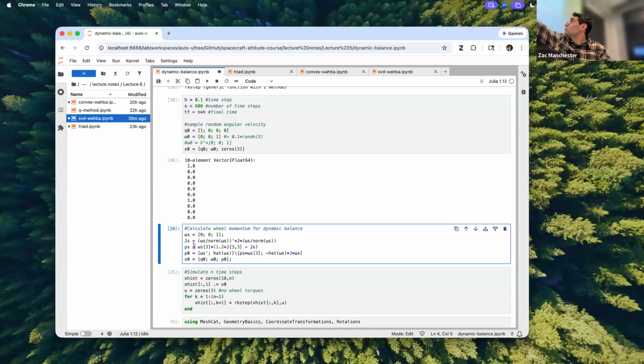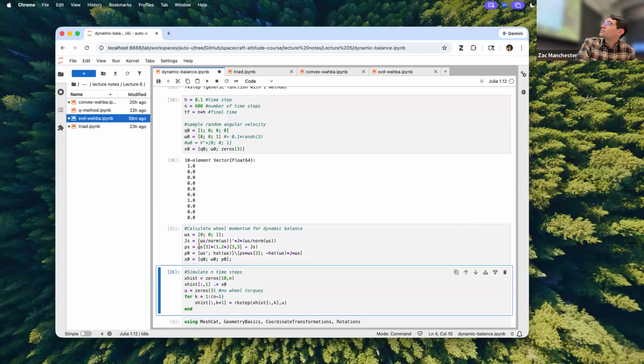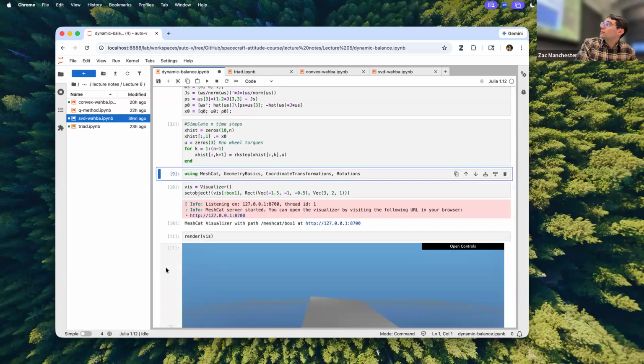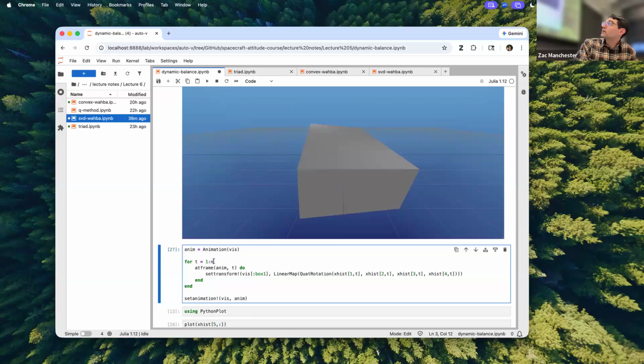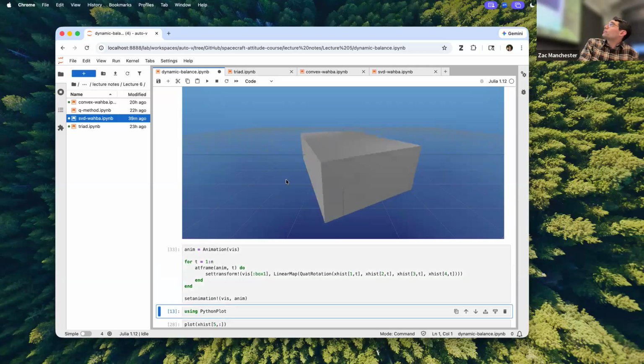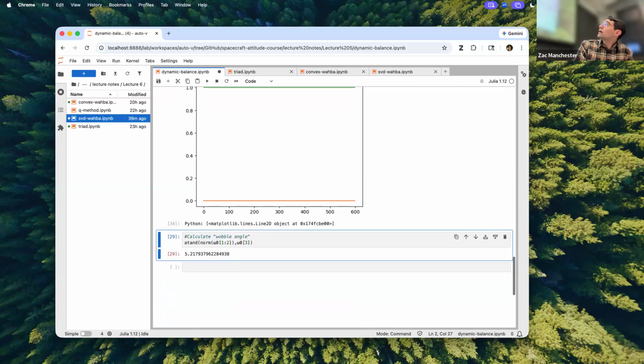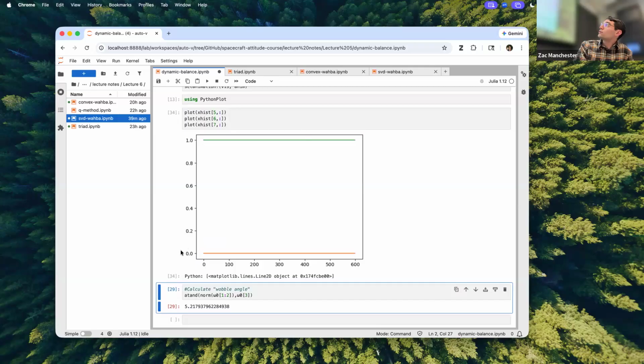We've got the desired spin, and basically what we're doing is figuring out the rho that will cancel out omega cross J omega so that we're making this an equilibrium. It's the same exact inertia, and now we're spinning it about the actual x-axis. We've done this dynamic balance trick so that now I'm spinning perfectly about the z-axis, no component in xy, and no nutation either, right?